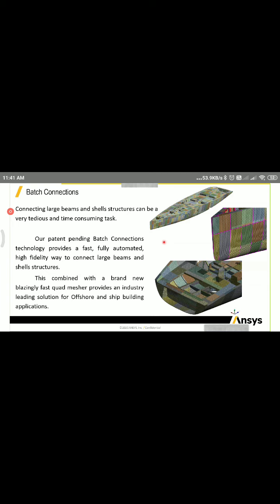So it depends on how the geometries are connected in realistic scenarios, and that's how you are going to set it. If you see the ship, all these things will either be riveted or connected together, right? There is nothing separate, or there is no hinge here. So that means it should be either bonded contact or node to node connected, and all these things will be taken care of in the batch settings.